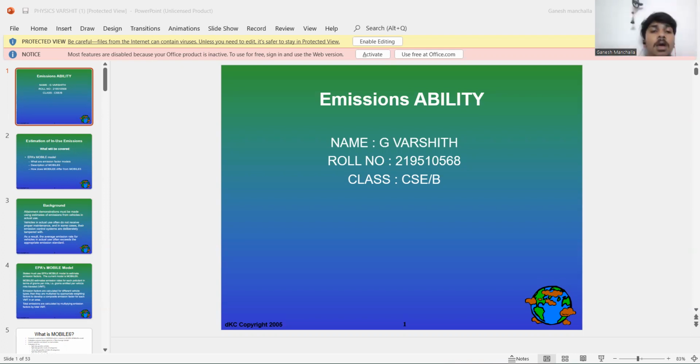Running MOBILE6. Prepare an M6 input file and save it from Windows. Double click on the M6 draft exe application icon. A DOS window will appear. Enter the input file name at the prompt. Remember to include the path if the input file is in a different directory folder than the run folder. Hit return.